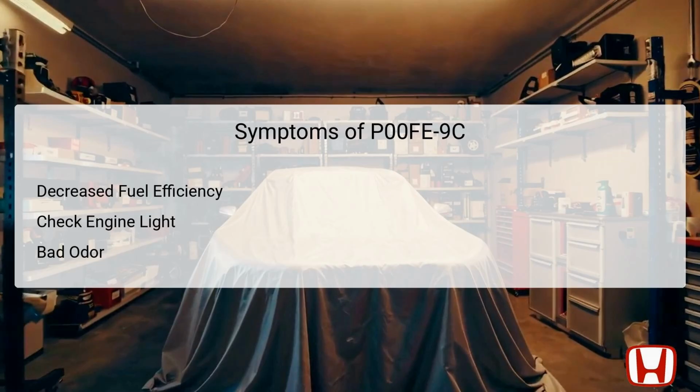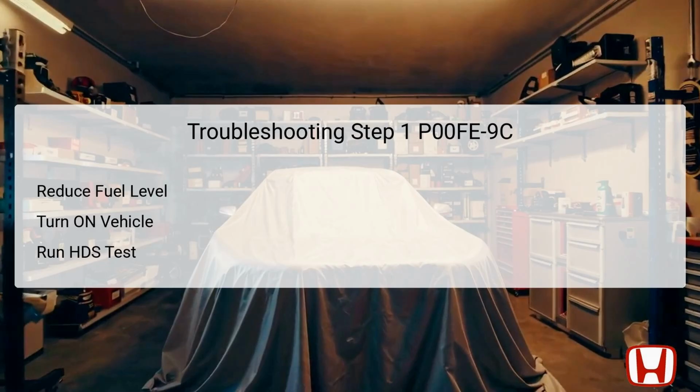EVAP system. Additionally, an unusual odor of gasoline may be detected, especially near the fuel tank area, indicating fuel vapor leakage. If left unaddressed, these symptoms may lead to further complications or even engine performance issues, stressing the importance of prompt diagnosis.